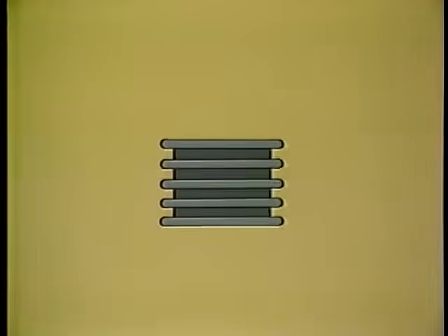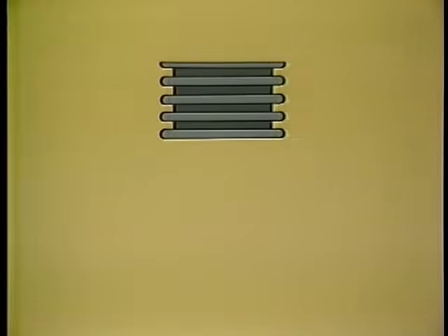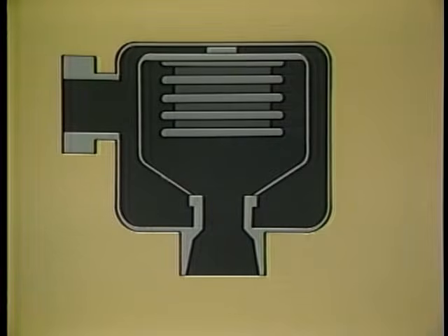Thermostatic traps are opened and closed by temperature changes of the liquids and gases inside them. One type of thermostatic steam trap is the bellows trap, named for the accordion-like cylinder that operates the valve. The bellows contains a liquid charge which vaporizes at or slightly below the boiling point of water. One end of the bellows is secured within the body of the trap. The valve is located at the opposite end of the bellows.